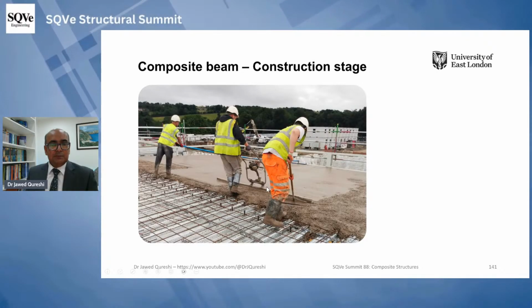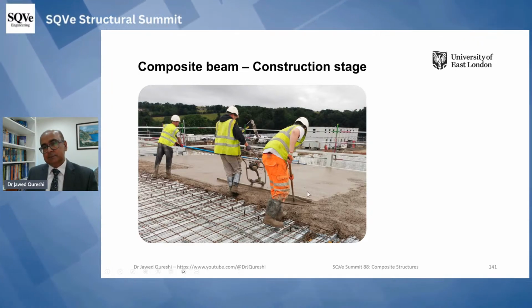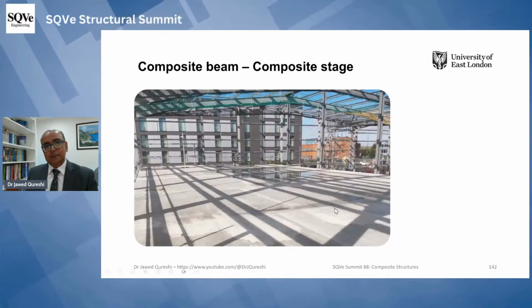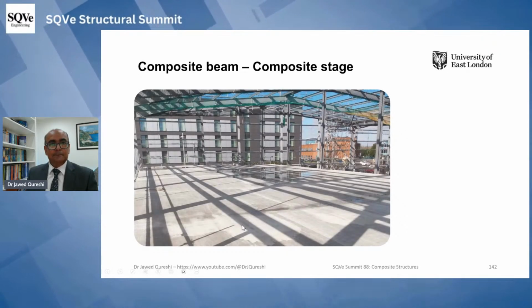This is the construction stage, where you can see that the decking has to support the load of these people, this machinery, and also the concrete. And this is the composite stage, when the concrete has hardened.